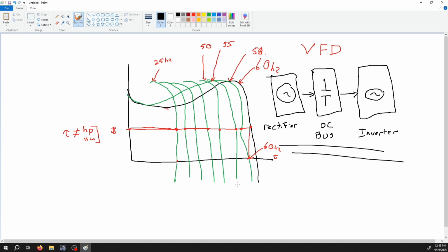And that's kind of the point of where we need to go today, because you need to understand that the motors themselves are all the same, and if you put a standard voltage at a fixed frequency onto an industrial motor, it is going to turn at its rated frequency. If you put a variable frequency drive there and change the frequency, you will change the speed. You will not limit your torque though, which is pretty cool.